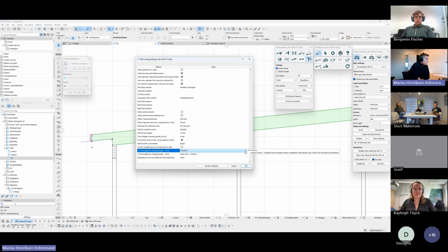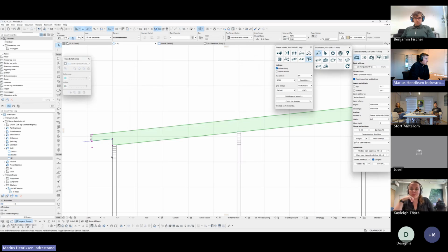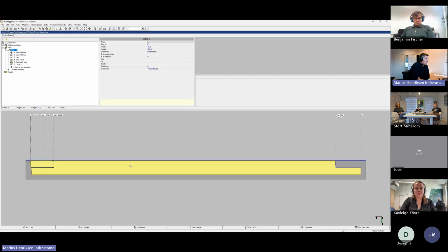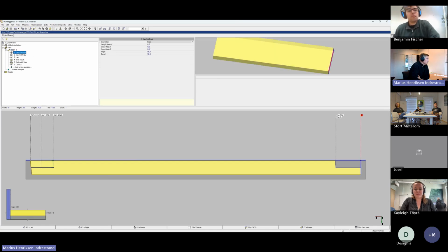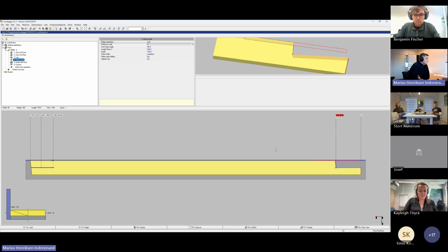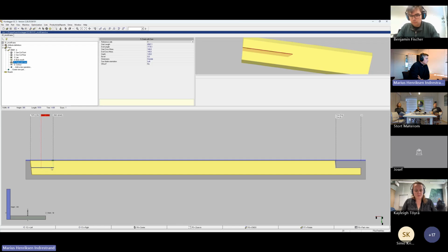Okay, so in this type, there will be no effect changing this. So I will have this on contour. Also, we will start off with the dado plus saw contour. Opening this in speed cut, you will see that there is no error message, and it will have a straight lap and then do the inclined bit with the bird's mouth. For the bottom piece of the rafter, there's a straight dado, and then there will be a contour here.